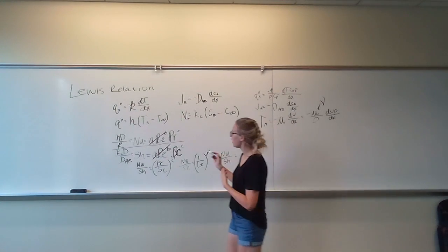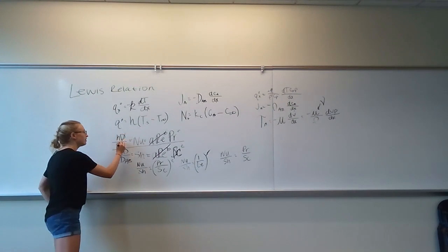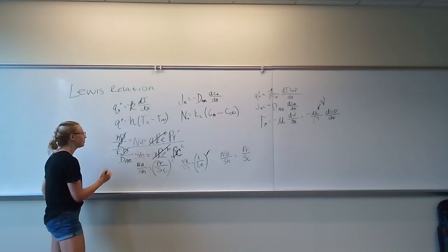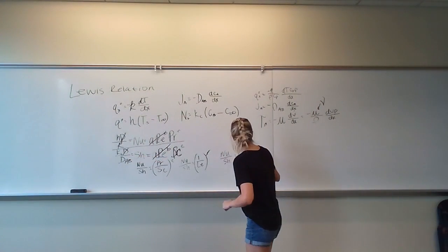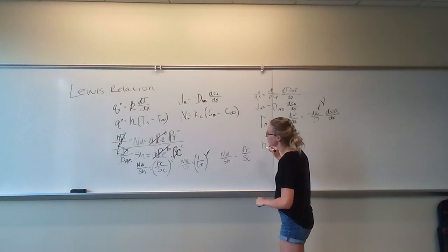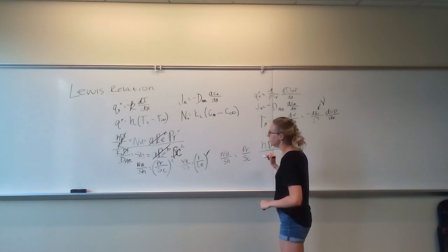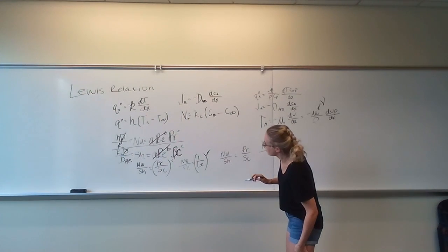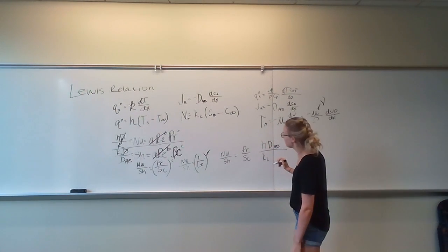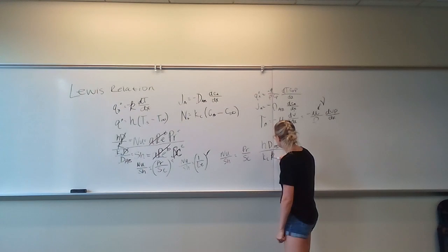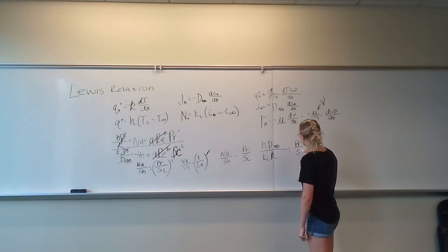So when we divide these two equations, the Nusselt number and the Sherwood number, the characteristic length D cancels out, and we get the heat transfer coefficient H times the diffusion coefficient dAB over the mass transfer coefficient Kc times the thermal diffusivity is equal to the Prandtl number over the Schmidt number.